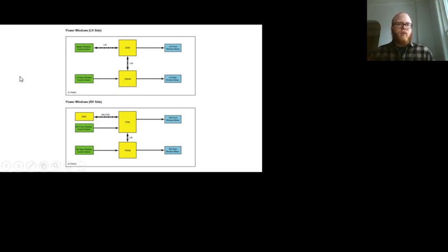The master module, like this master control switch, just sends out information saying, hey, the guy pushed the driver window down button, or the guy pushed the driver window auto down button, and it just sends that information to the driver's door module. The driver's door module does not respond, doesn't send any information back to the switch. It just receives more than just a simple voltage change. It sees like a little Morse code that is giving it a little bit more information, seeing as one-touch windows are becoming really popular.